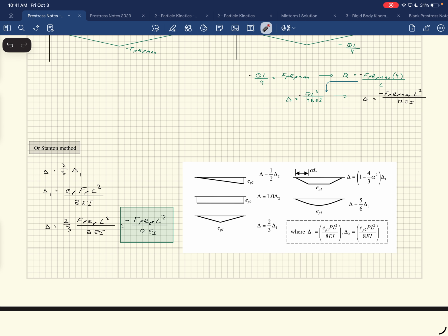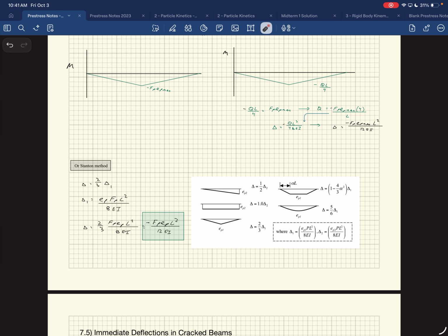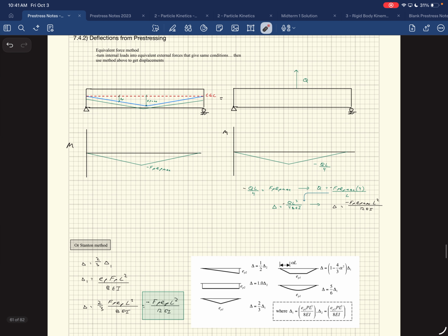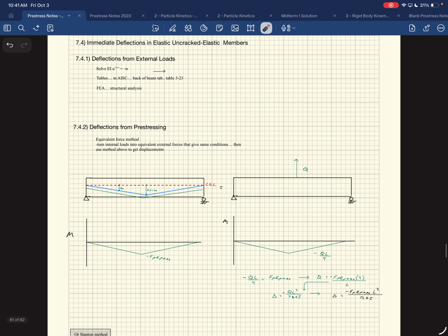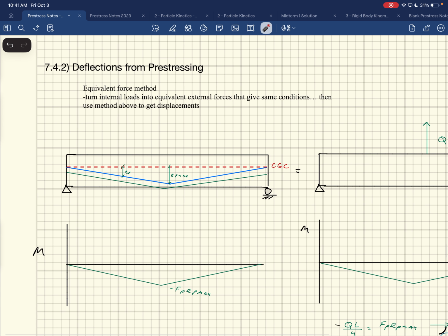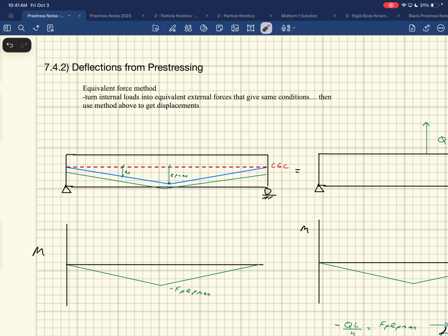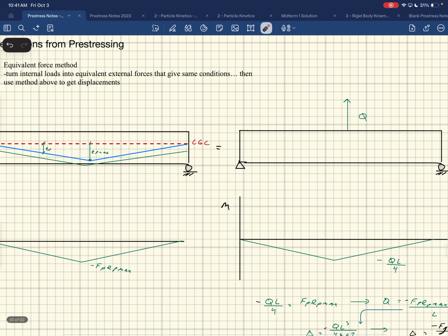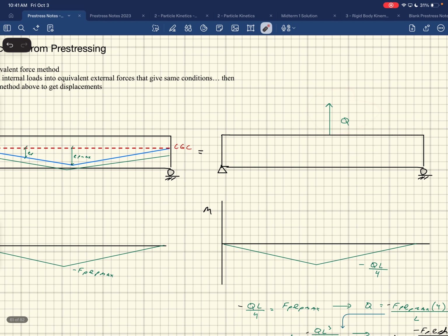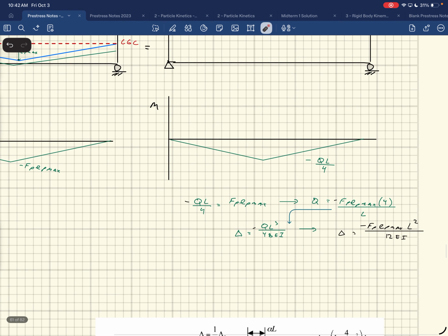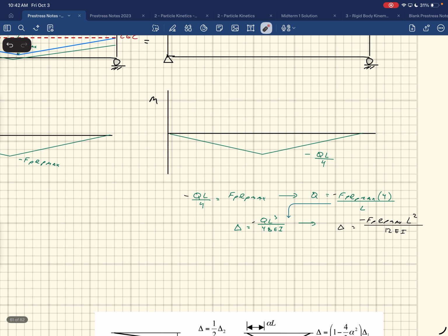And so if you were to do this with finite element analysis, and you were like, okay, I'm going to model this thing using finite element analysis, which post-tension floor design has built into it. You could do that. If you're using VA to do this, it doesn't have a way of putting tendons in it, right? But what you would do is put in the regular loads on your structure, and then you would put a point load on it in the middle, just like this, that would have the magnitude of this. You would put that equivalent force.